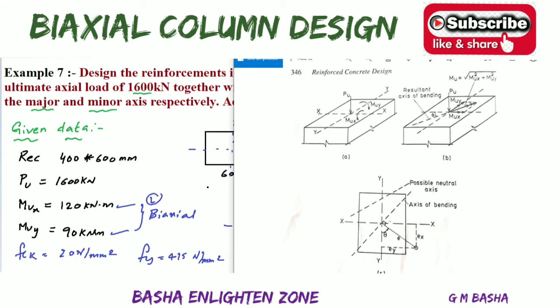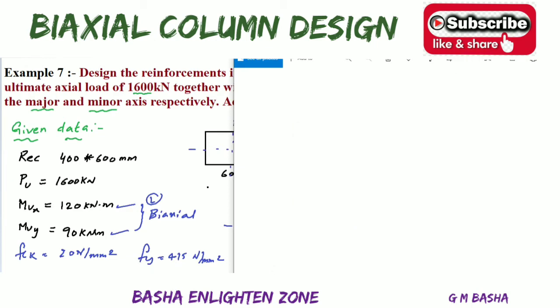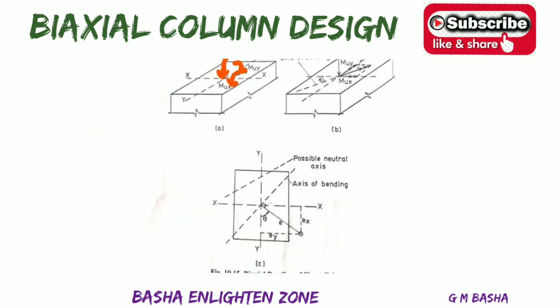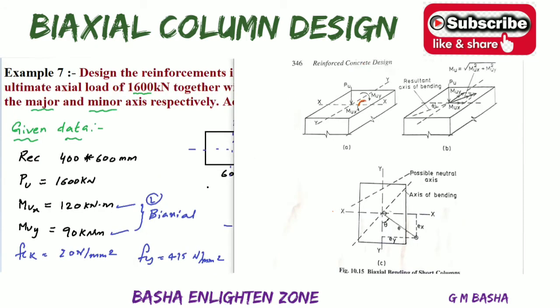So here the moment is acting on both, so here there will be an axial loaded column, and the moments acting along one will be x and another will be y. So you see the difference. See here, the moments will be developed both on the x axis and y axis, meaning two additional moments are developed. So that is the biaxial condition.